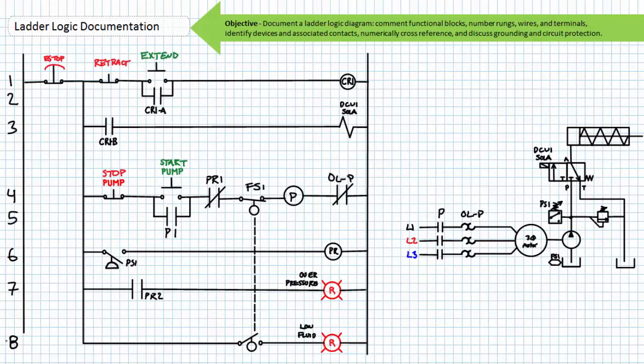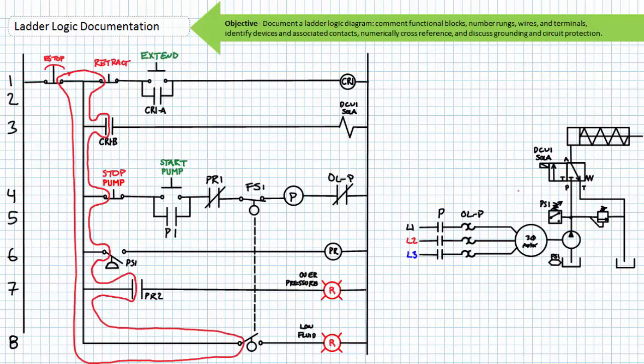This is where things get interesting, because there are a lot of different methods of doing so, 2 of which I'll show here. First, don't think of them as wires, but rather nodes. Recall that a node is a common point of connection. Note that the right terminal of the e-stop is connected to a bunch of other devices. This is a common point of connection, and all devices hooked to this single pool should have the same voltage with reference to another point. That's really the purpose of wire numbering.